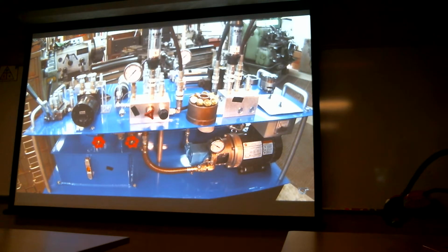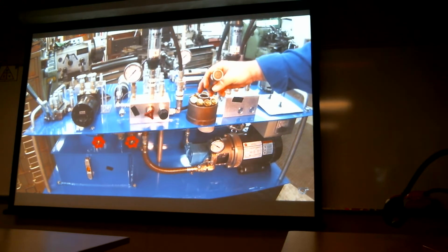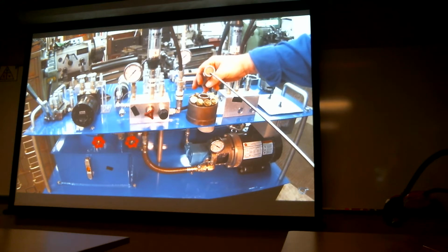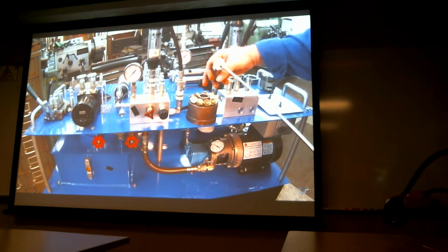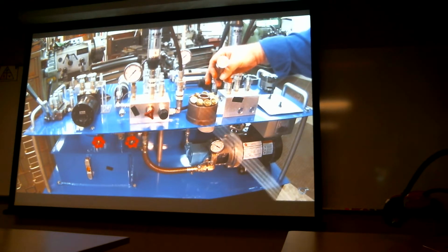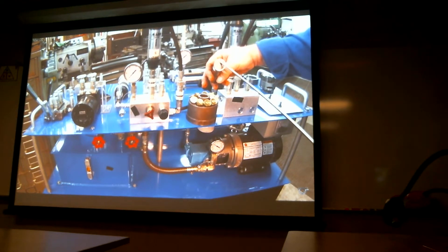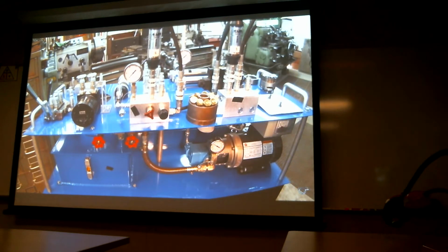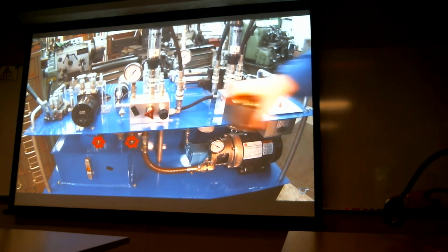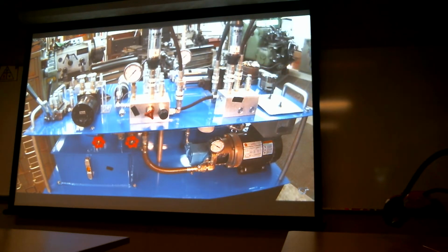And here's a larger version of that, so hopefully you can see that. That little tiny hole right there in the middle of this piston is how it lubricates itself as it spins around on what's called a swash plate, okay? When you starve your pump for fluid, that oil doesn't come through that little hole, and you get what's called cavitation, okay? And as your pump cavitates, this is what happens to it. Those little pretty black shoes melt, okay?